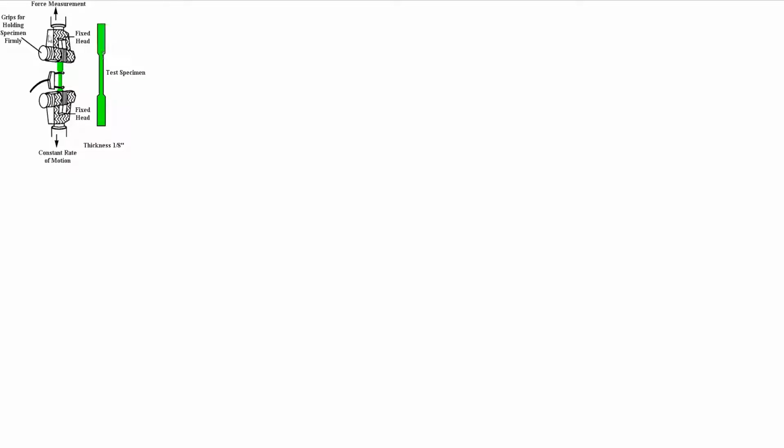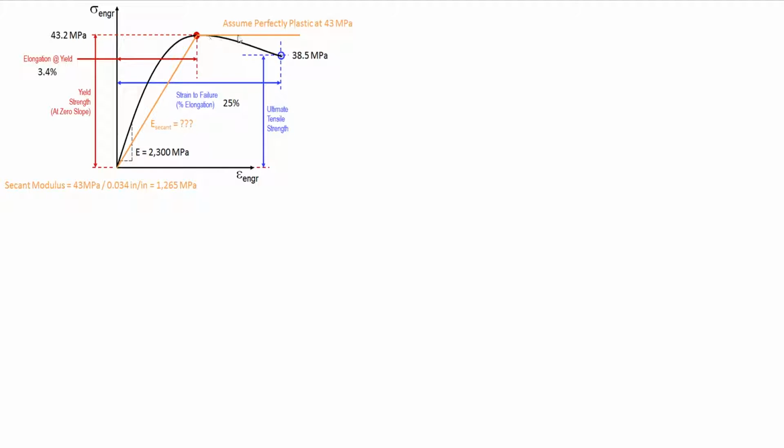That's when you have 3 points of testing, or flex. You have two supporting pins, and then you have this piece, which is basically a modified version of this with just a pin on it, and it'll push down on the material. So it's basically this horizontal piece, and then a piece comes down this way and pushes on it. The sample will bow with compression in the top and tension in the bottom, and it'll do the same thing. It'll measure how far it's moved as your deformation, and also how much force it's putting down. Both of those options will render you a graph that looks something like this.